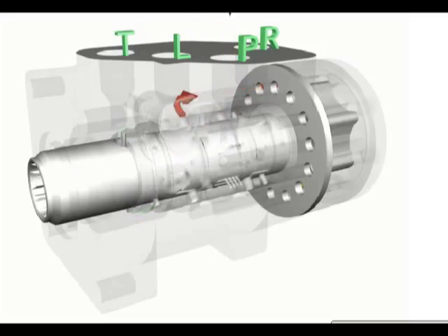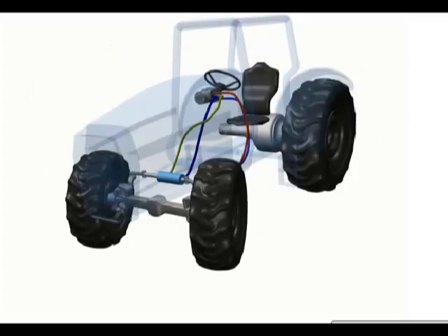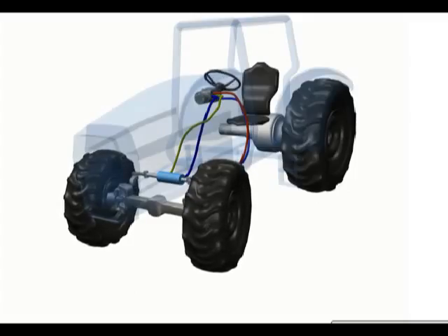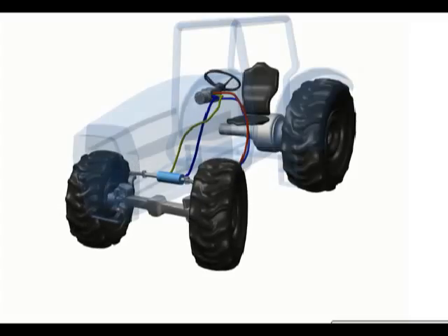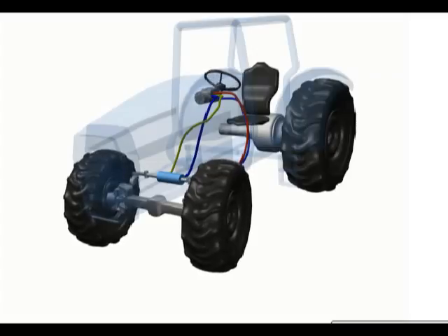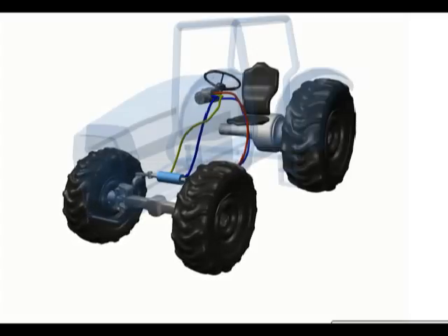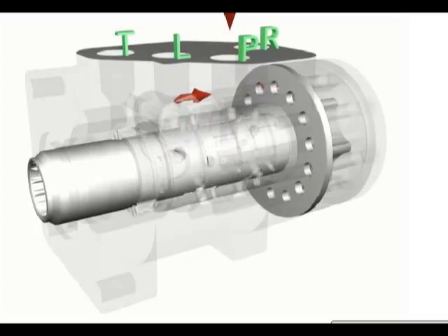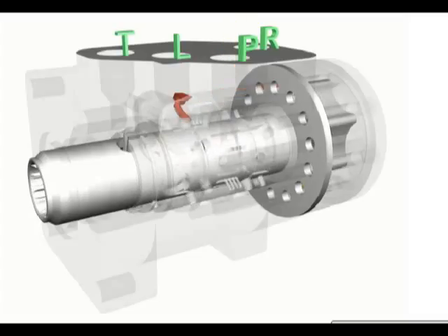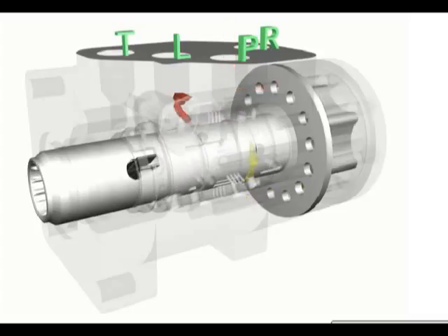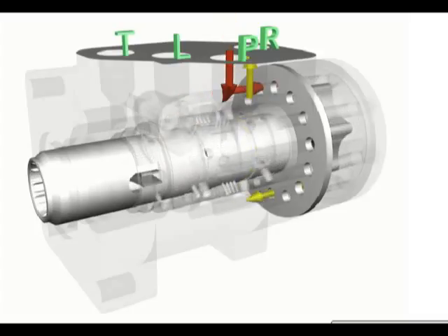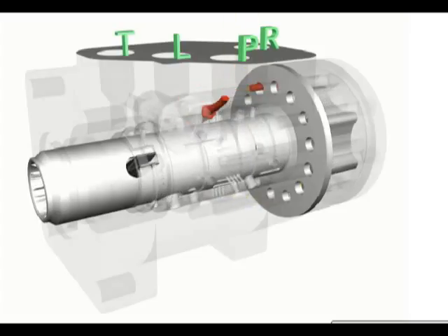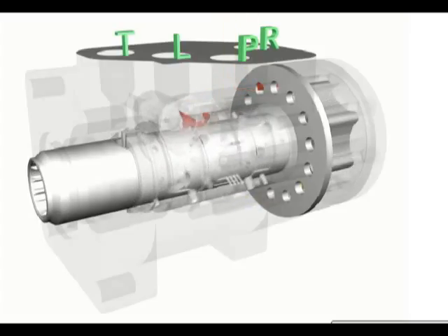Fluid flow turns the wheels in the opposite direction. Pump flow not used in the steering circuit passes through the tank port of the unit to the reservoir and to other downstream functions through the power beyond port of the unit if provisions are made for this option.